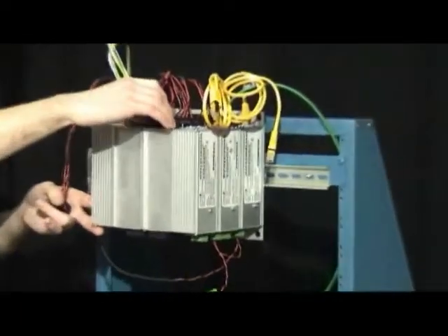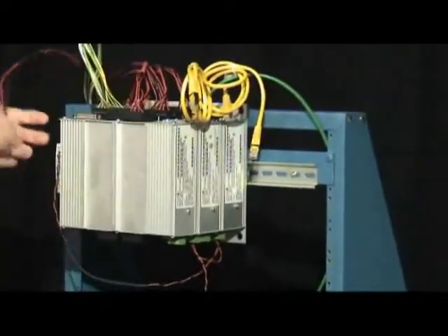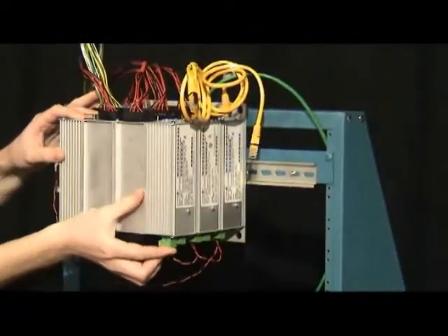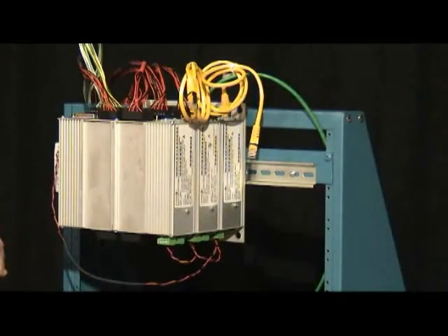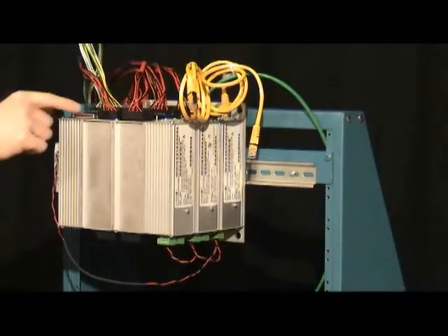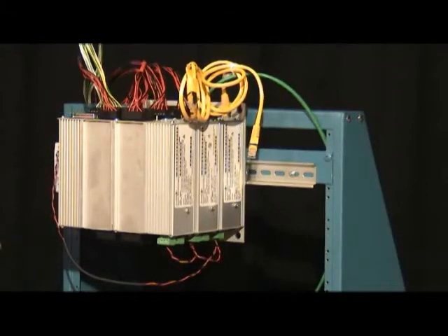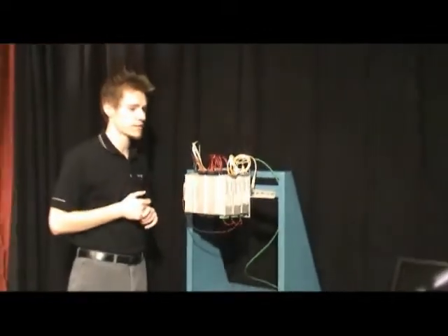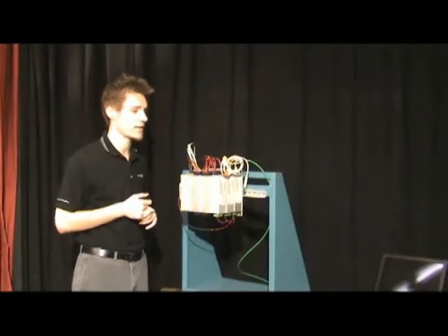First, you just plug your sensor signals into the pluggable terminal blocks here. Now your power signal also comes in through a pluggable terminal block on the bottom. Now with the voltage input and output units, you can also use the optional DB25 connector to connect to any of our line of 8B isolation amplifiers to provide up to 1500 volts of channel-to-channel isolation. This is also beneficial in that if a fault anomaly does occur that surpasses the capabilities of the 1500 volt isolation, each 8B module is easily accessible and affordable to replace, leaving your Acromag unit and other channels intact.